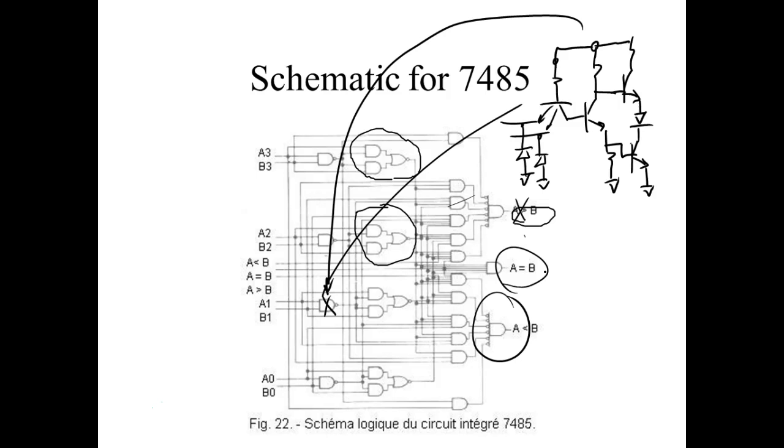That makes sense? So if I got my milling machine and I put a number over here and it keeps flying, it goes from left to right and it keeps flying, and it don't stop when they're equal, then I know I've probably got a problem with this guy right here, right? Either that or one of these inputs over here are messed up. So that would be what I would come up and figure this out. So I don't need to know the actual makeup of these things. All I need to know is what the guy does. What is it supposed to do? If it don't do what it's supposed to do, I don't go in there and replace a single transistor. I don't go in there and replace a single gate. I just replace the whole item.